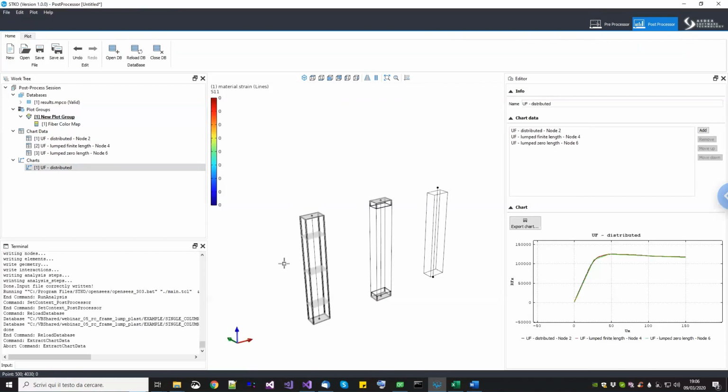Okay, so whenever you have to do elastic things with a constant cross-section, it's easier to use the elastic beam column because you can just use the elastic cross-section. Otherwise, if you want to use the force beam column, you also need to specify the integration scheme and other stuff. But this is a minor difference in this case. Okay, let me see if we have other questions.